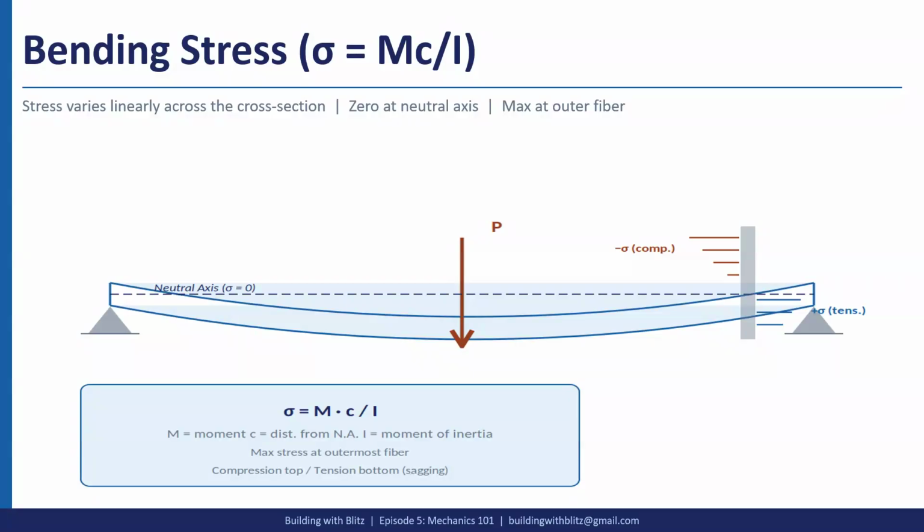So that's why a lot of times for bridges, where you have a lot of moment, or some really heavy buildings, you have deep beams rather than wide beams, because you're getting more bending resistance out of that member to resist the moment. That's a little more on the design side, but think of the inverse of bending stress: the resistance that a member provides comes from that moment of inertia, really the height, in summary.